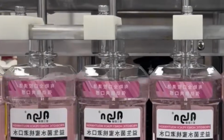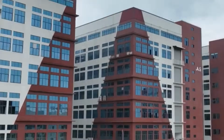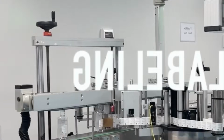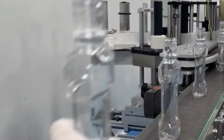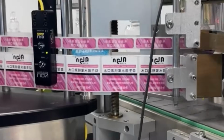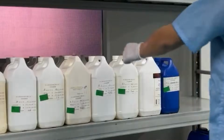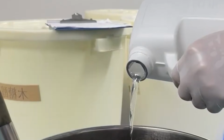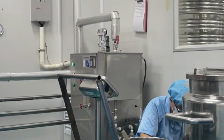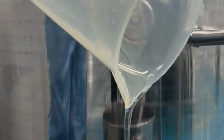Mouthwash production begins with the preparation of purified water, which serves as the base solvent for all ingredients. The water undergoes reverse osmosis, filtration, followed by ultraviolet sterilization. Conductivity meters and microbial sensors ensure that the water meets pharmaceutical grade specifications before being stored in stainless steel holding tanks equipped with continuous recirculation systems to prevent stagnation.